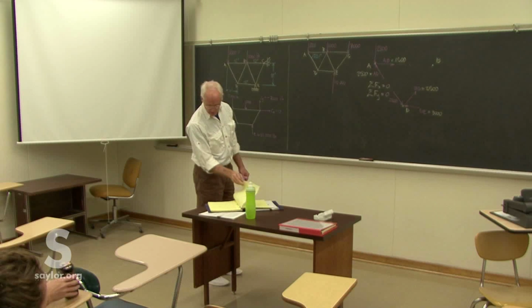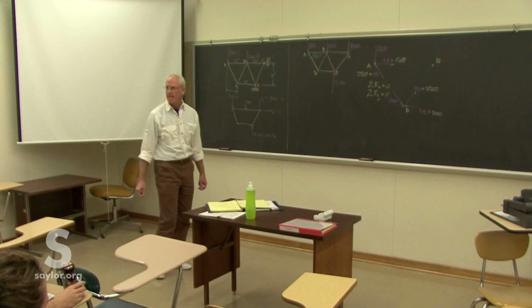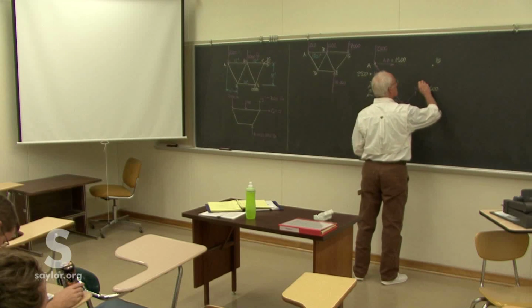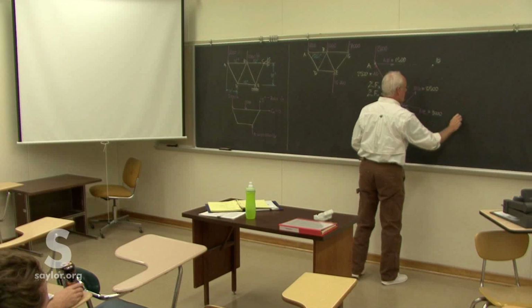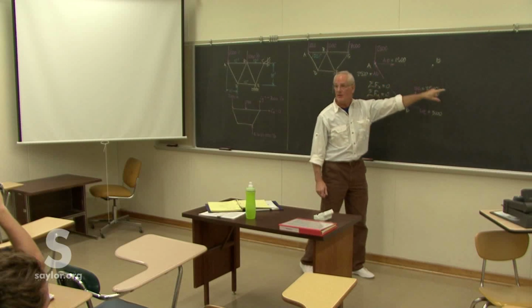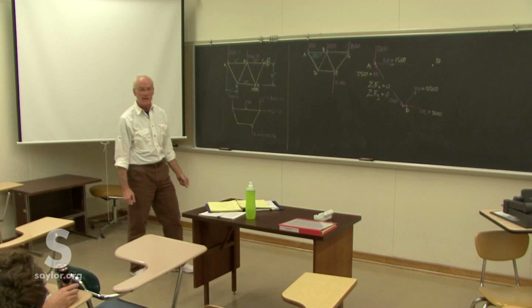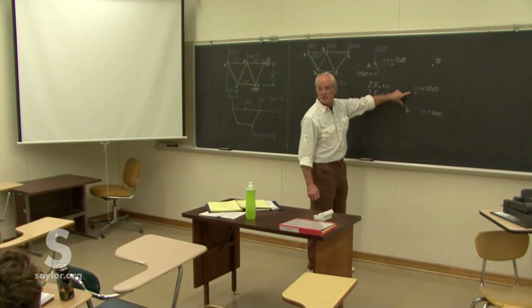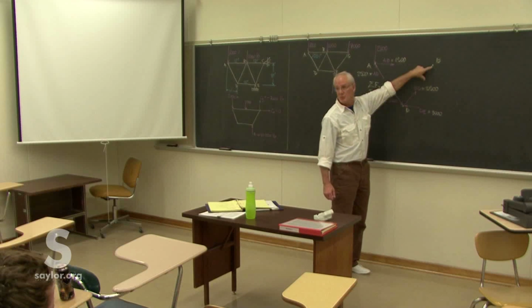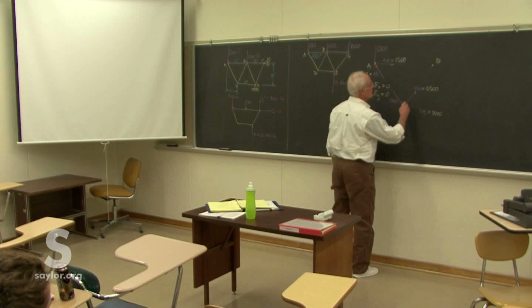Now, can we do joint B? Yes. We can go up to B, and again, my recommendation is draw the joints as you solve them about where they lay, at least in the same spatial organization. You're just less likely to make a mistake. It's much easier to transfer the force that you found down here on joint D up to joint B where it next acts if you draw it this way. Much less likely to make a mistake.